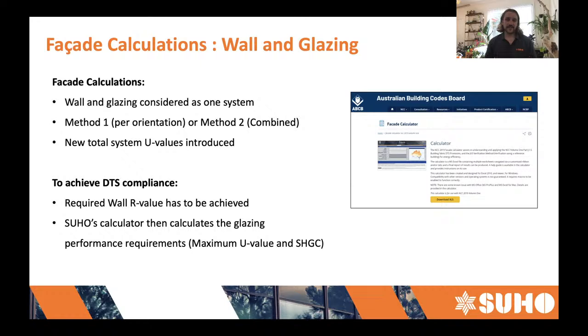So for most daytime operating buildings, the U value requirement is a U value of 2, which is equivalent to an R value of R0.5. So it's not something that's too crazy, but it's the fact that you've got glazing, which traditionally doesn't perform very well at all, particularly in Australian glass, which might be between a U value of 3 and a U value of 7 on the really cheap single glazed units.